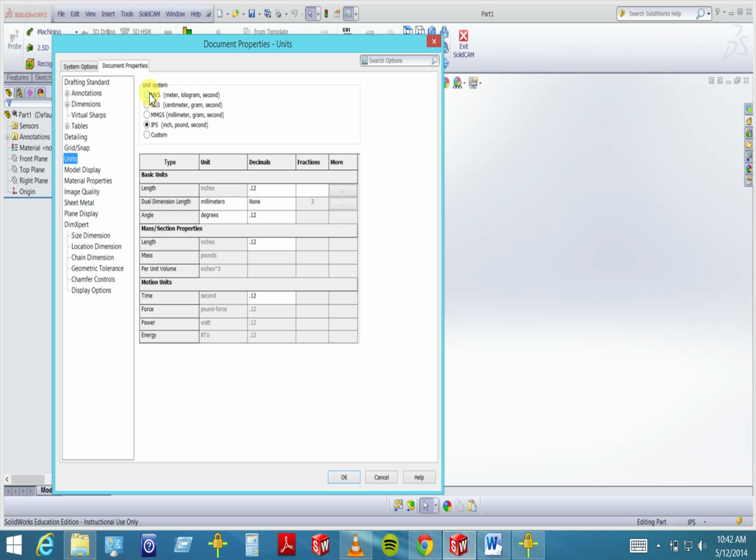A millimeter is 0.0394 inches. It doesn't matter if you call it an inch or you call it a millimeter, it's the same size. The decimal equivalent is the same. So my advice to you is, if you like metric, which you probably do, you can probably build all your models in metric units. There are going to be some things that you should do in imperial units or their metric equivalent. And like I said, it's going to be fasteners mostly, and standard sizes of materials.